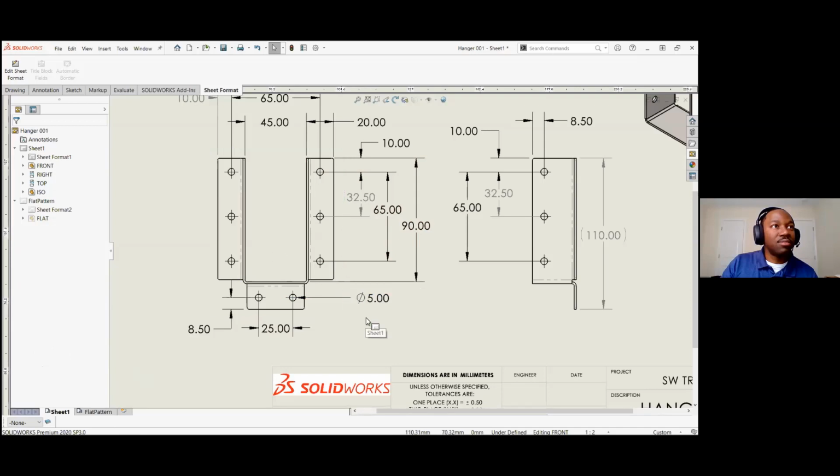Yeah. And then Danny's got a question. What do you save the drawing as if you were sending it to someone? Is it normal SOLIDWORKS save without models loaded? Let's see. Danny, I might just save it as a PDF if you wanted to really be the lightest weight version to send somebody. There are options. You could send them the native SOLIDWORKS drawing. They could only open it in detailing mode if they didn't have the models present. Might be an option.